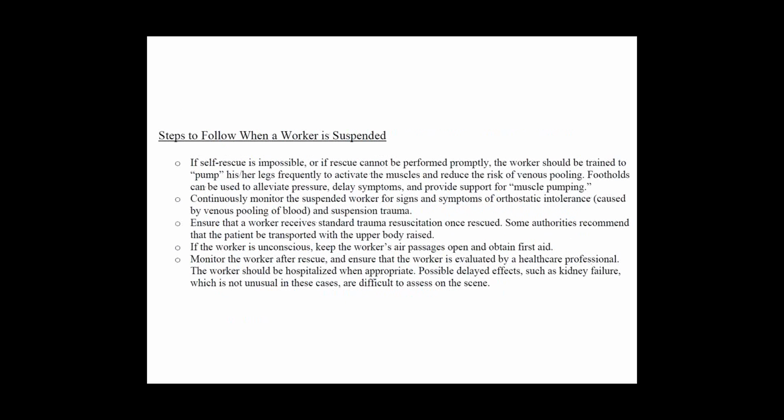And if the worker is suspended, we have to take into consideration how to deal with that. If we have suspended trauma, we have steps that we need to be trained in on how to engage in rescuing the worker from suspended trauma. So we need to reduce the risk of venous pooling. We need to elevate the feet to alleviate the pressure, delay symptoms, and provide support for muscle pumping. So there's criteria here on this tip sheet that gives us information on how to deal with suspended trauma.